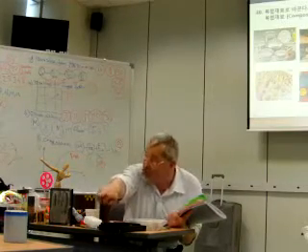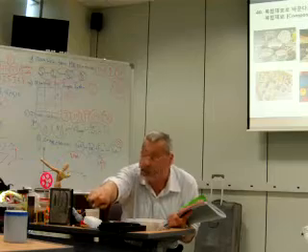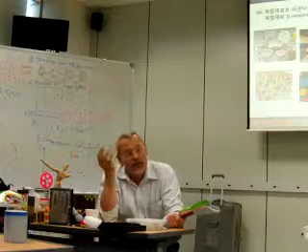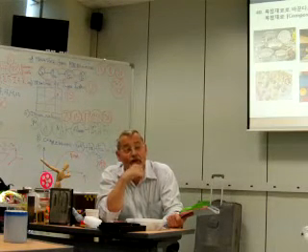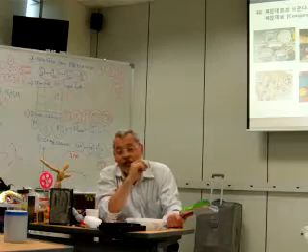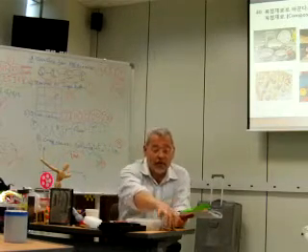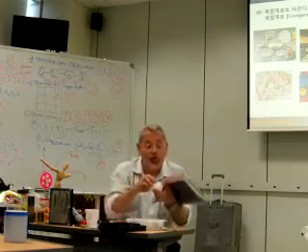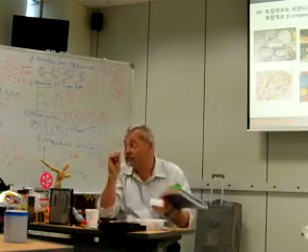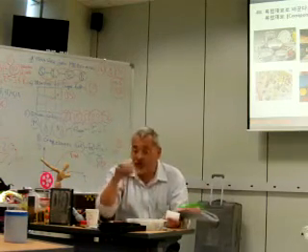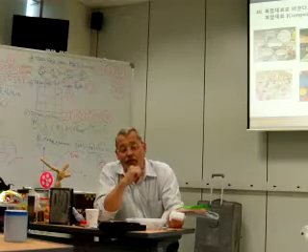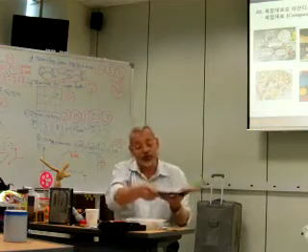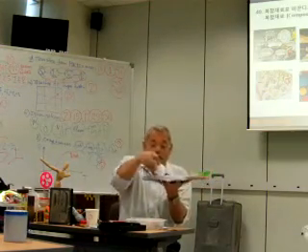For example, thermal sensitive ink in this object is a smart material. I can explain to you another smart material, thixotropic materials. Thixotropic materials are materials with changing viscosity. If you have mechanical stress, you can obtain a jump of viscosity. And it is very useful during the coloration process, during manufacture of PCB, because when you manufacture PCB, you deliver some ink.